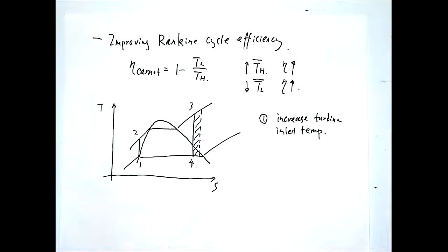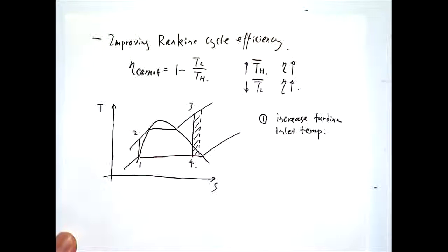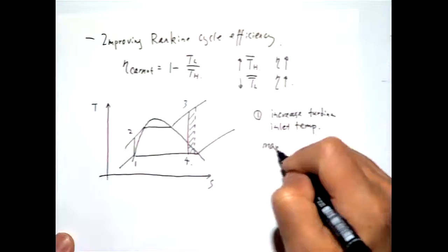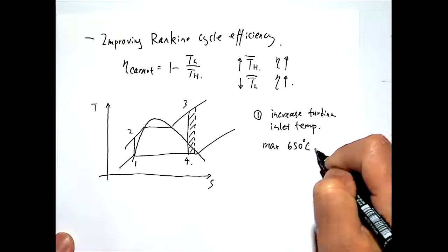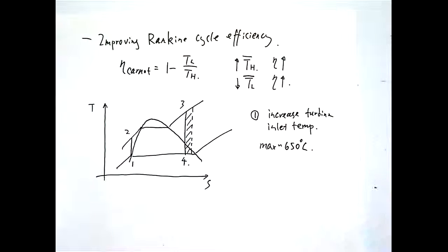We see that already from the ideal gas power cycle there. So this indeed has been used, and similar to the gas turbine case, the temperature of the steam turbine has already been raised to the maximum level that the material can handle. So today the maximum temperature is around 650 degrees C, already raised to the limit that the material, the steam blade, or the boiler can handle.